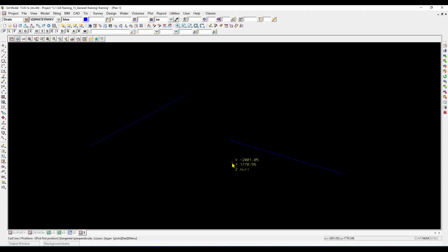If there is a point nearby, it will pick the point. And there is a search radius as well, which you can change in the settings. So if there's a point, it'll pick the point. If there's no point within the search range, it will look for a line and snap to the line and finish drawing or doing what you're doing on that line. If there's no line, then it'll just select the cursor position and finish your option there. So just so you know, be wary of using fast accept until you've gotten quite familiar with it.